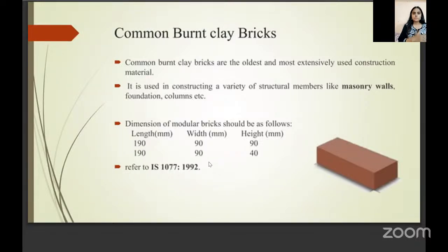Traditional bricks were used earlier in load bearing buildings, and their size was slightly larger, not a lot, but very slightly. But nowadays, the kind of bricks that we use for construction are known as modular bricks. These modular bricks can be made either with clay or with fly ash as well, or any other material. The standard size of modular clay brick is 190 cross 90 cross 90.